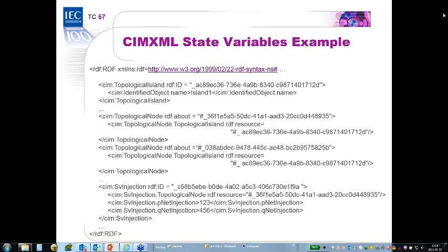This partitioning, in the current specification of 61970-452, you will find the concept of a model authority set. Now, in this framework drawing, there are 6 model authority sets. Actually it's the model parts here for the 3 frames, and I didn't mention, but when you actually populate a boundary, that's also populated by a model part, and you can have multiple model parts that define boundaries. This would especially happen, as Larsola was pointing out, when you go forward in time and some new tie line gets built.